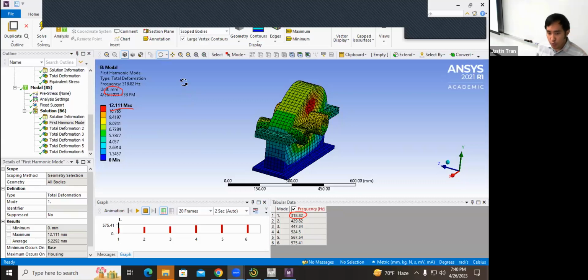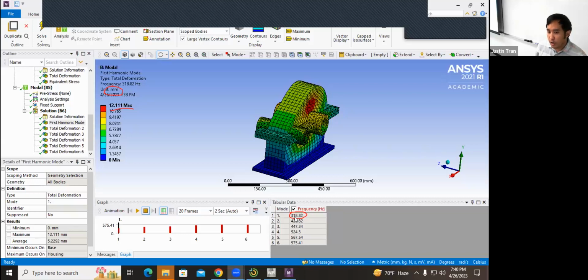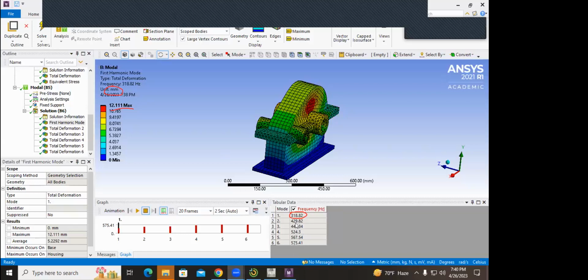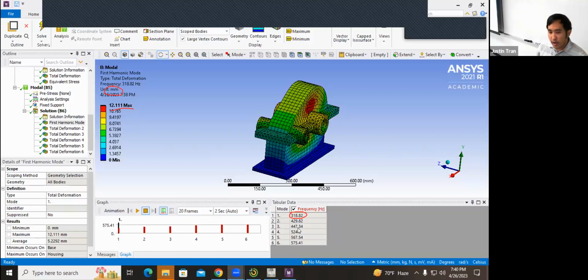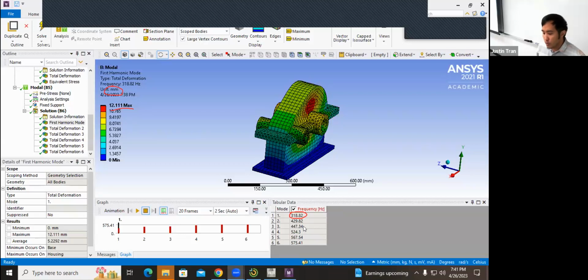So the first resonant mode here is probably the most important one. That's the one that people are concerned with, and it's going to be approached first. Exactly. But you technically still get resonance at all these other ones. Yeah, all those values are bad. But usually you're not going to get into this range over here. There are circumstances where you can, but for the most part, you're interested in the first one. And usually the first one is going to have the highest magnitude of resonance as well. As you get to the higher resonant modes, the amplitude kind of dies down.